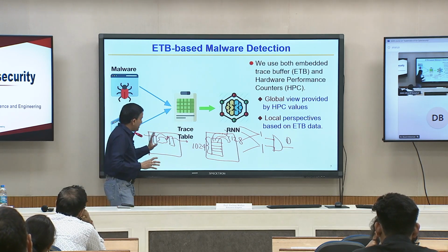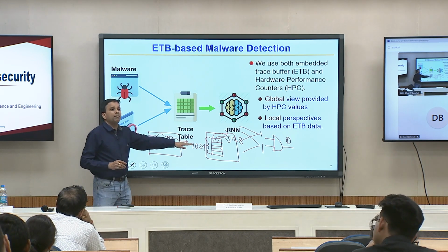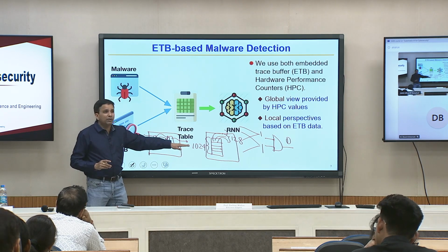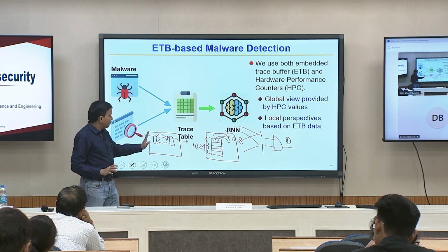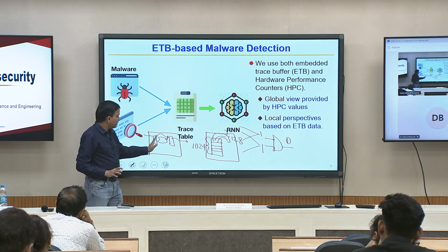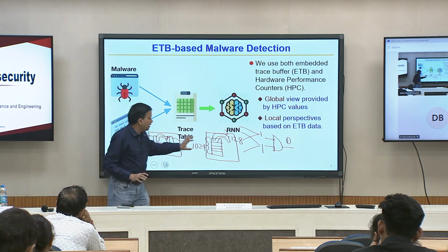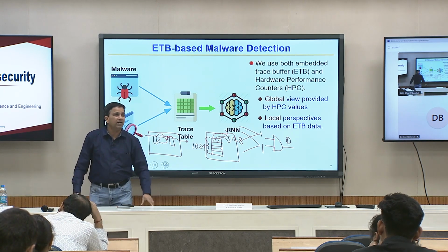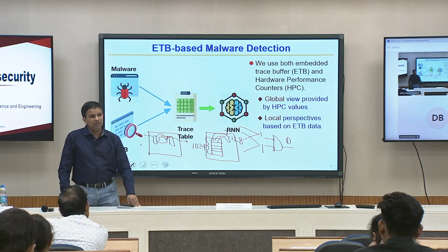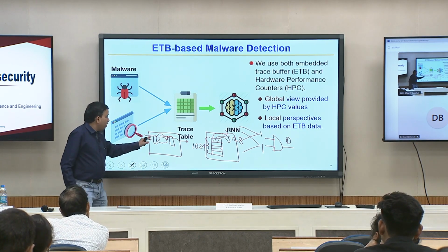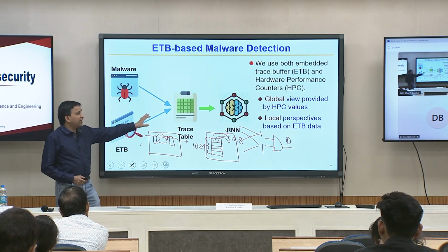So, that is why the scan chain idea was invented: you keep pumping data, whatever values, and it goes through a chain. If you have a million flip flops, it will take a million clock cycles, which is a lot, but that is still guaranteed. If you do not do that, and you pump something in, the sequential and combinational logic computes and produces something, then with a depth of 5, 10, 20 or 100, it takes a non-deterministic amount of time to initialize all the flip flops. A lot of attackers make use of the scan chain also, but this time we are only talking about how, as a defender, you want to use it.